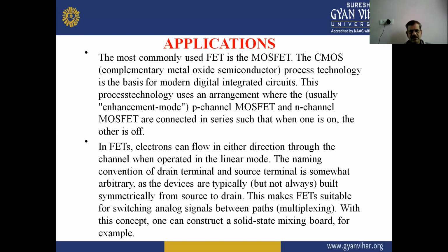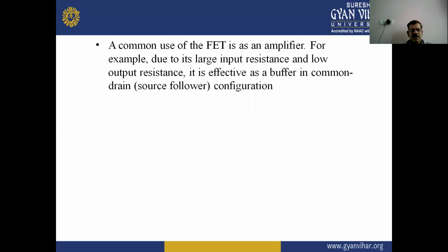For example, a common use of the FET is as an amplifier. Due to its large input resistance and low output resistance, it is effective as a buffer in common drain or source follower configurations.